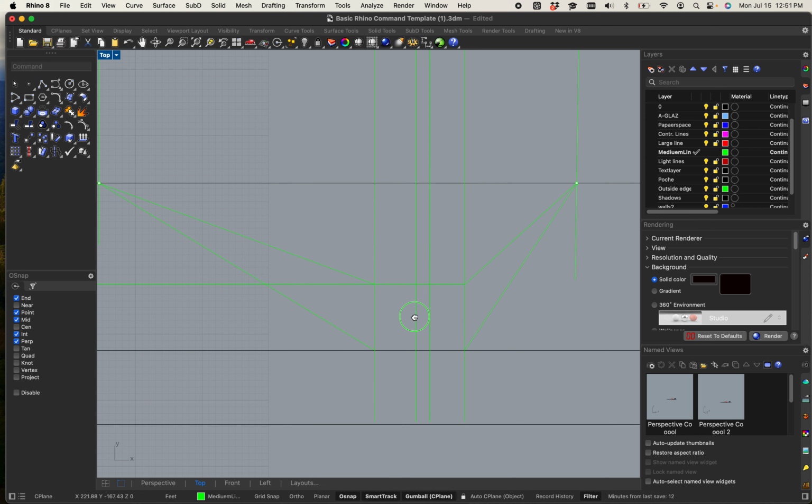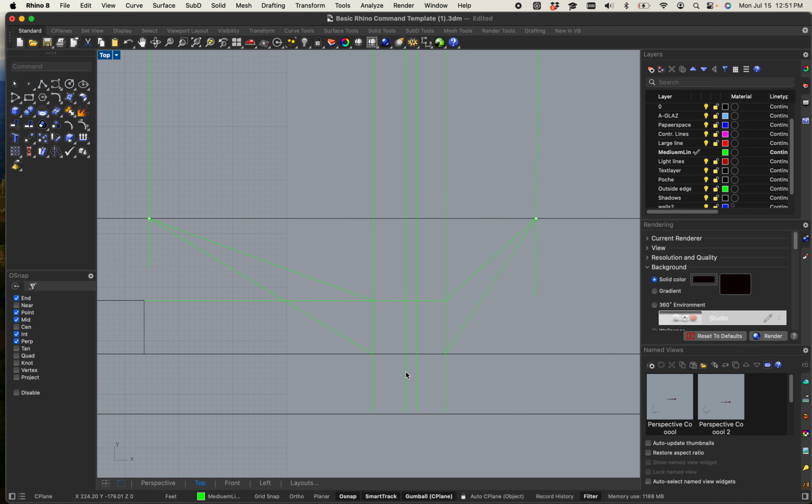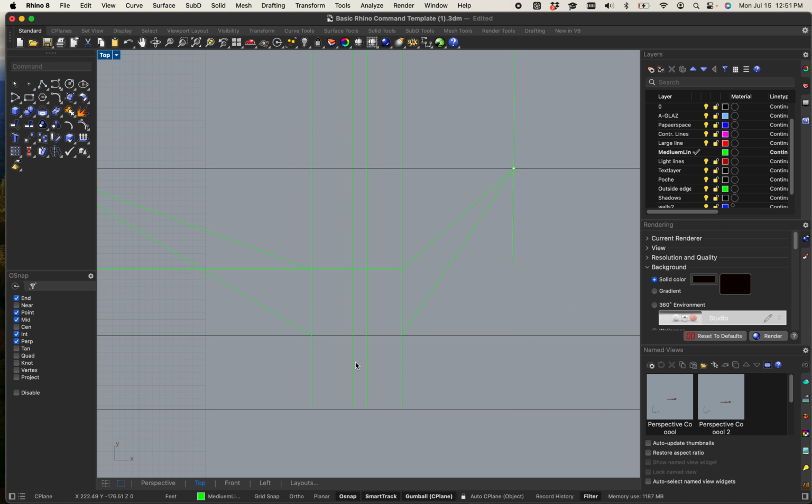So another tool that's pretty nice about this is, well, I got to these points, but I don't exactly know where to extend them to, right? And maybe it's not a defined position. Don't get me wrong, in this case, I think it actually stops on one of these lines. But if I didn't know what that was going to do, I could also use fillet. Fillet is where it takes two lines and turns them into a corner or a radius.